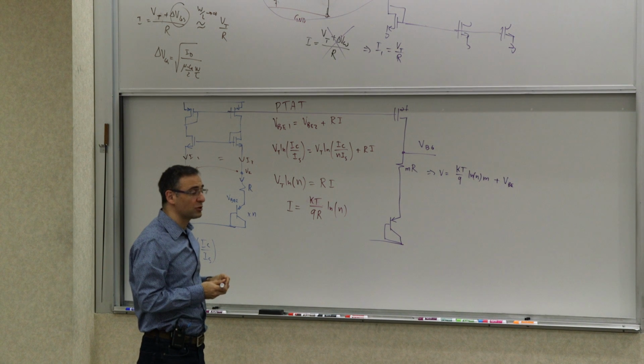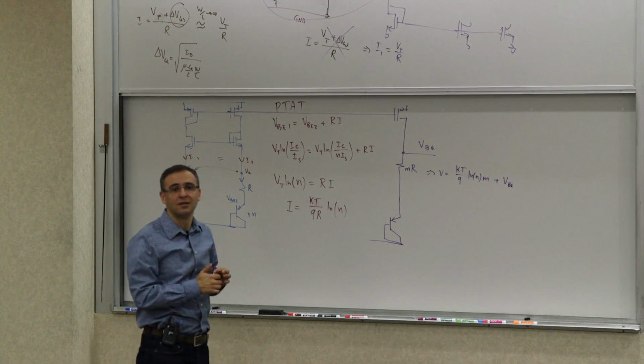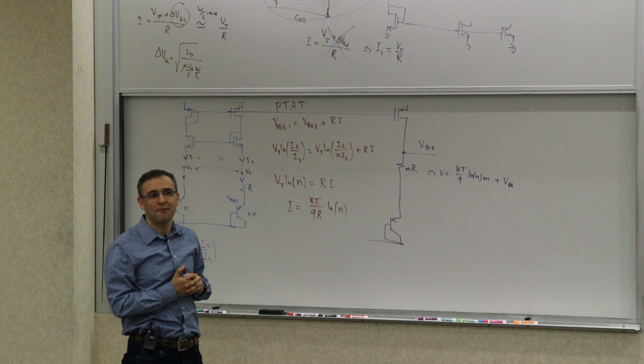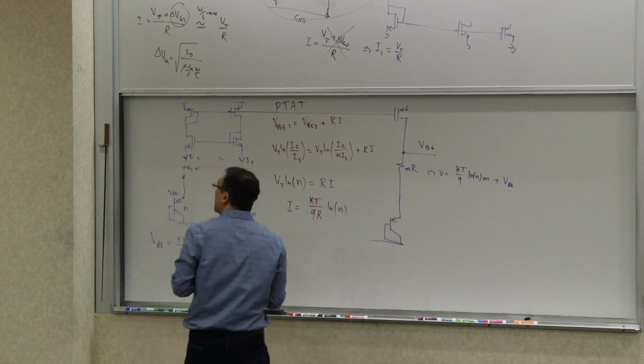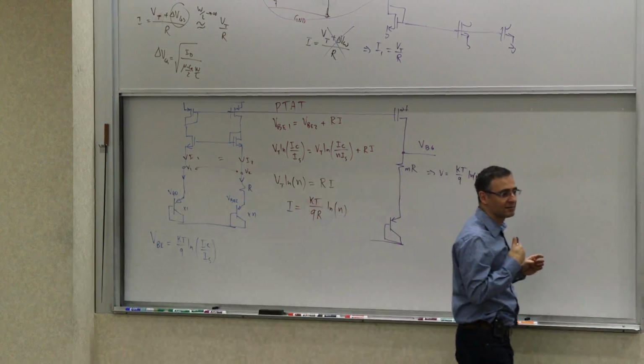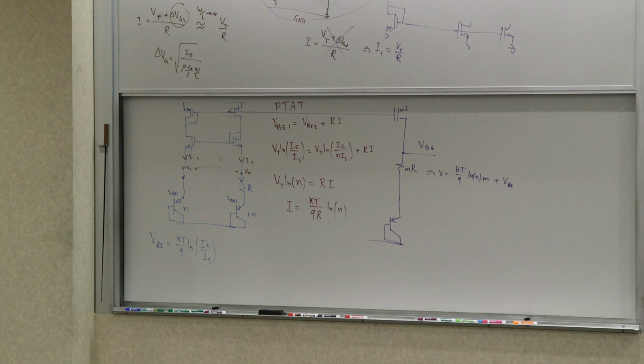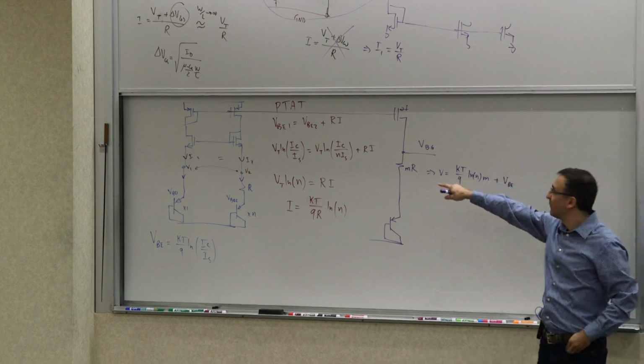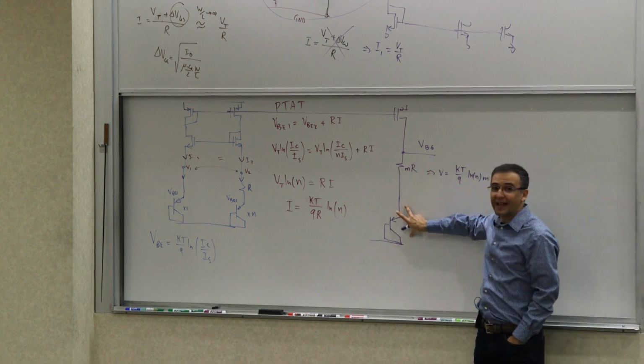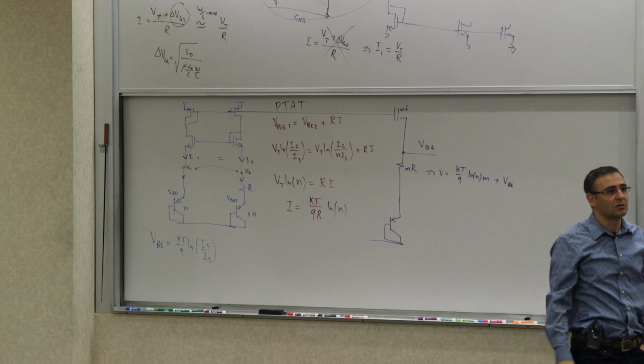And this way you can actually produce something that's called a band gap reference. It's very insensitive to the supply voltage and temperature and things of that. So you can actually make this first order. You can try to cancel these two dependencies by applying the right amount of PTAT to it and adding the right amount of proportional to the negative.